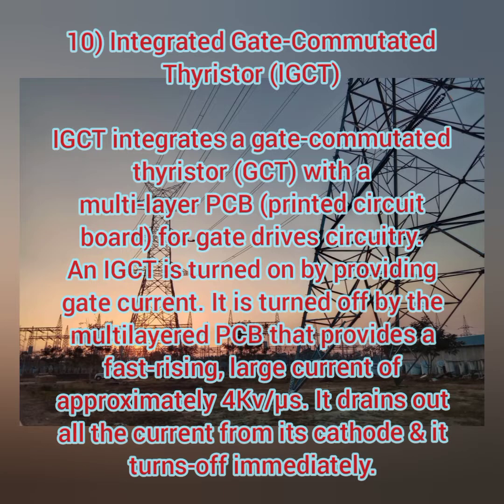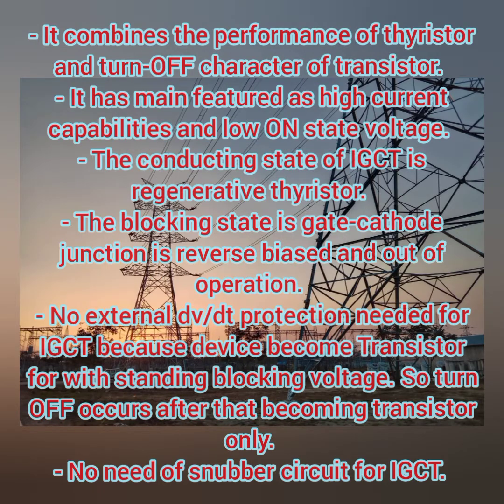So this IGCT is your advanced thyristor triggering module. Then it combines the performance of a thyristor and the turn off characteristic of your transistors. It has main features of high current capability and also a low on state voltage.